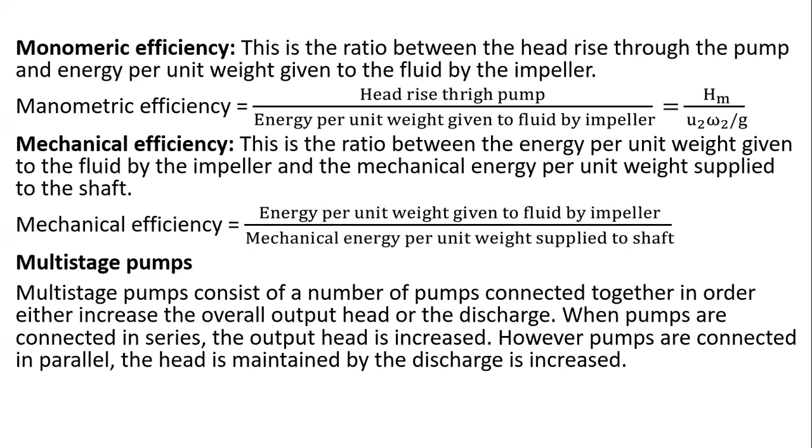Then we can also decide to connect them in parallel. Here, it could be the same height you're dealing with, but the rate of flow will be increased, because you have a number of pumps that are pumping fluid from the same source and then delivering it to one reservoir, or to one end where it is being collected.